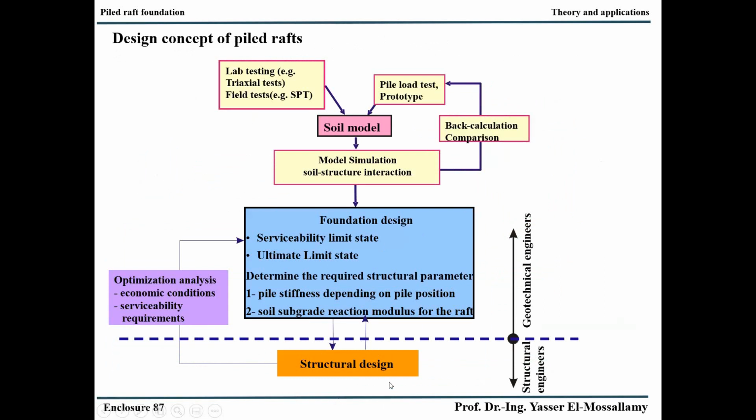Normally, the work of the structure is huge and they are above us, but because we speak now about foundation, therefore I make more details for our work, and our structural engineers is here. But we have all this interface between us. We cannot work separately. We should work hand in hand. We should make site investigation, laboratory test, pilot test, back calculation from case histories. We can do a lot of work here to reach at the end a realistic model of the soil and conduct our soil structure interaction analysis.